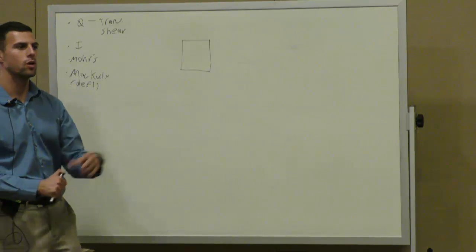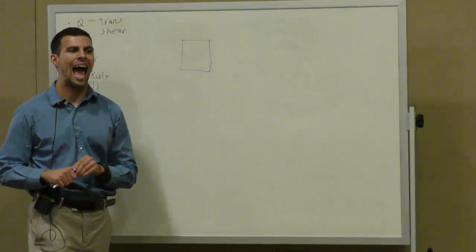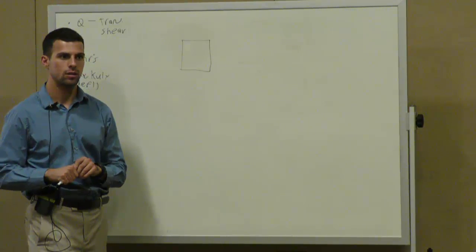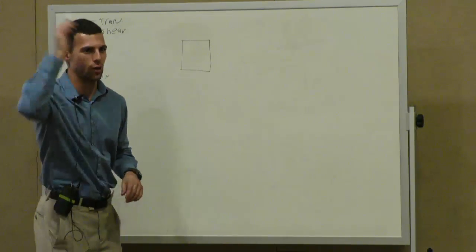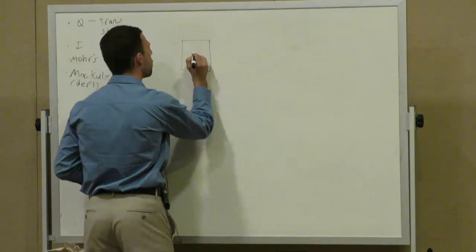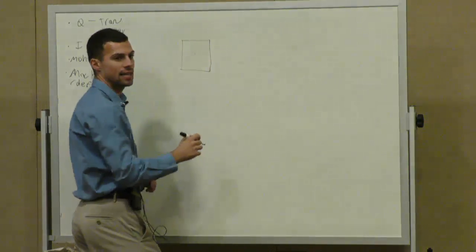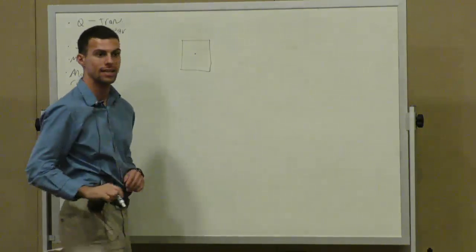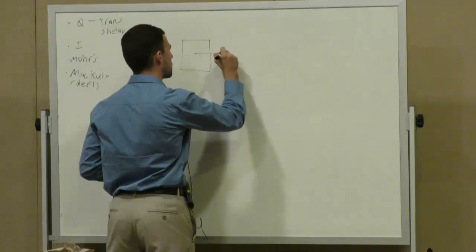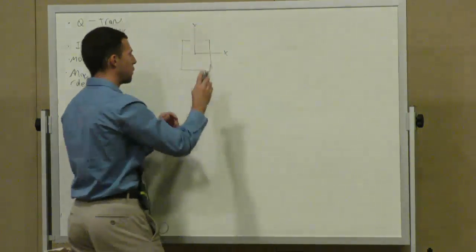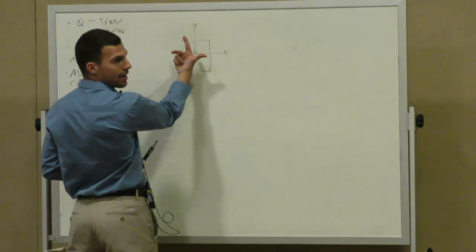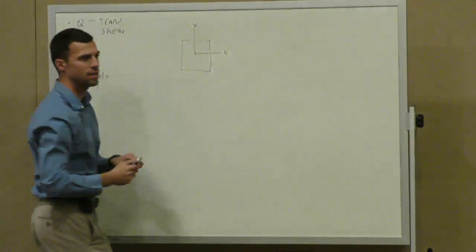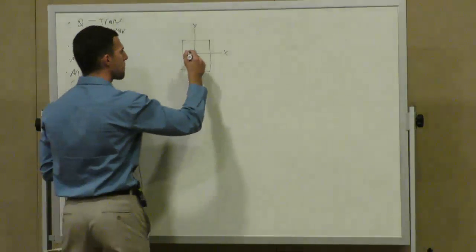In other words, where do we a lot of times see things acting around? Centroid, right? Not center, centroid. Everything here is centroid. Everything has area. So let's put our origin at the centroid, and so let's establish some coordinate systems. So if we have x over this way, y over this way, and then positive z would be out of the board, using a right-hand rule. So we have positive z coming out of the board.